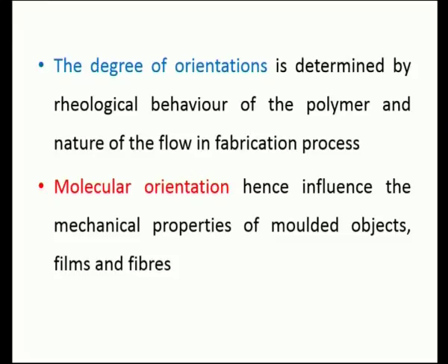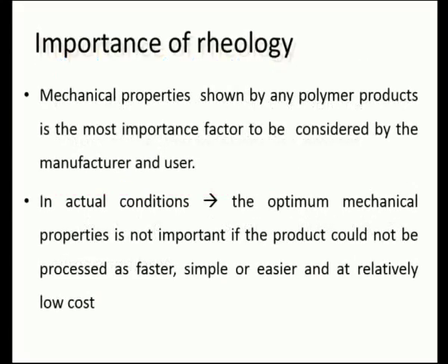The degree of orientation here refers to the entangled polymeric chains. When subjected to high temperature and then to shear, they get oriented in a particular direction, which facilitates easier flow. And molecular orientation does have an effect on the mechanical properties. If it is oriented in the drawn direction, its mechanical properties are very high compared to the transverse direction. Of course, the mechanical properties are the most important properties required for any polymeric products.